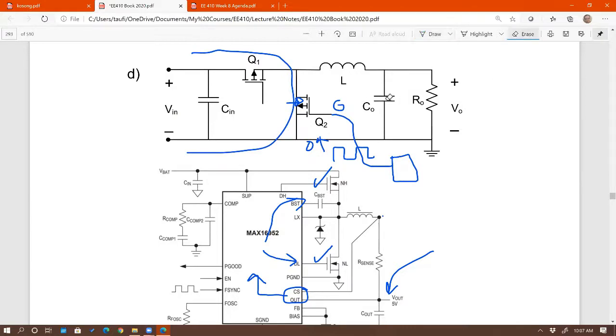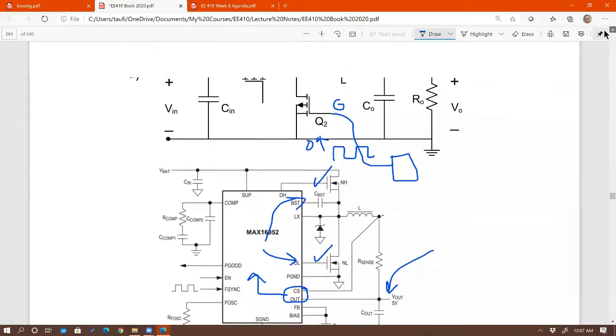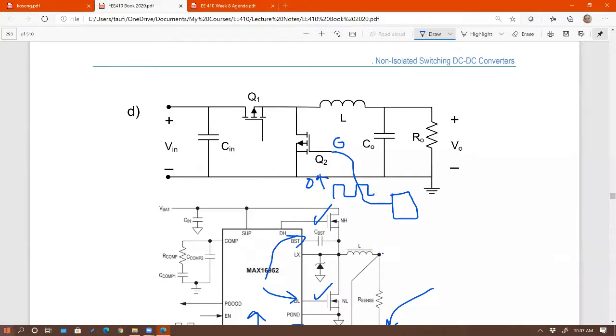If you do that. So that would just be implemented using a simple NOT gate. And then there's also logic that provides dead time between the two. There are small timings that are very important. It's called dead time. So if this is for the top MOSFET, the bottom MOSFET will be the complement of that.